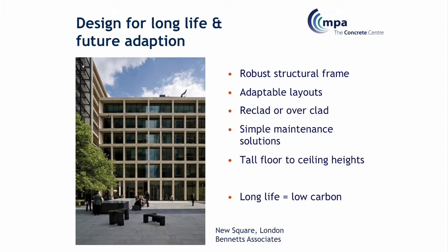Clearly it is an important factor and something to consider. That structural frame could have its cladding removed and be reclad using something that's more efficient or just different or appropriate to the new building use. Consideration of the structural frame, its adaptability, future layouts. That robust structure has a capability of lasting for very much longer than its initial design life. Obviously, tall floor-to-ceiling heights are important as well, particularly if you're going to be naturally ventilated, but also to allow future adaptability for other building types.